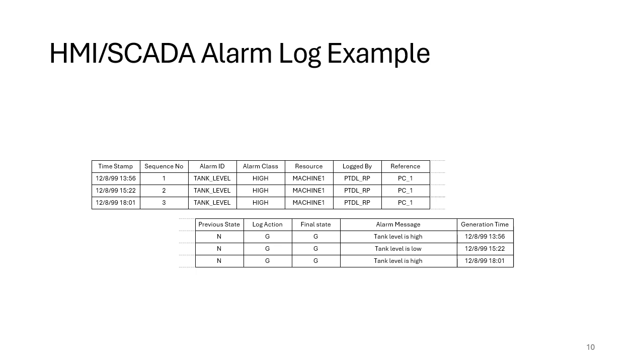The benefit of coordinating against GMT or UTC is that that doesn't have any daylight saving times, so you get an actual absolute alarm time. Whereas if you're using the current local time, then 2 times a year you might find either there's a 1 hour gap when the clocks go forward, or when the clocks go back, you might even get duplicated alarms because the clock goes back by 1 hour at that time of year. So that's an additional aspect with timing, is additional columns for local and UTC time.